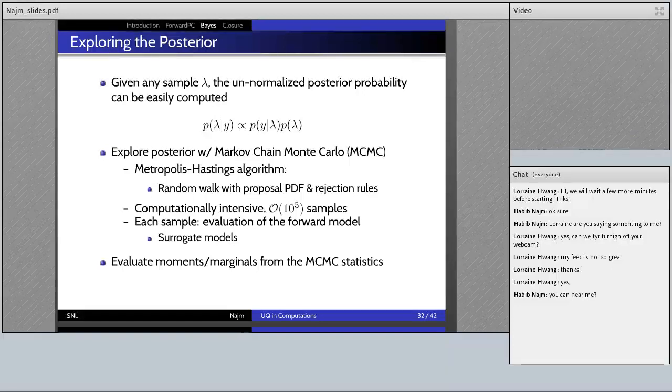And quite often this discrepancy is due mostly to instrument noise, and we can model it as a random variable because it originates in noise. For many instruments, you can be sure what the character of the noise is, and it's frequently Gaussian. So let's say epsilon is Gaussian as shown at the bottom.